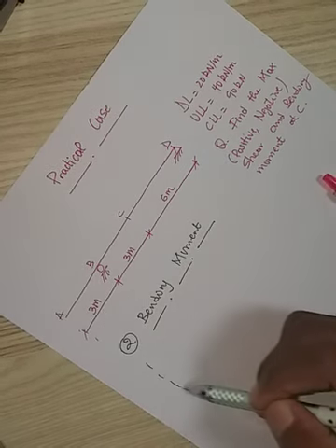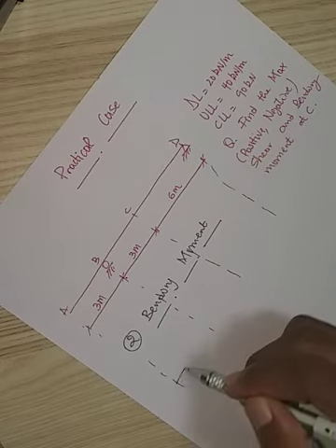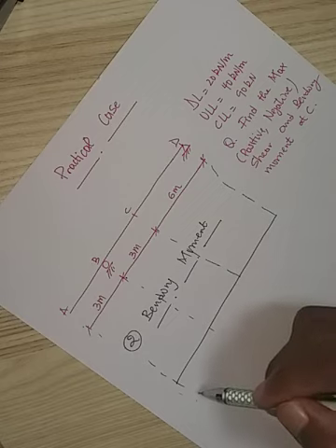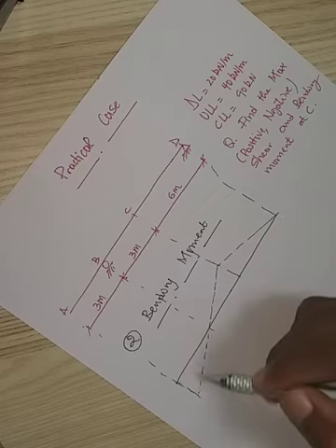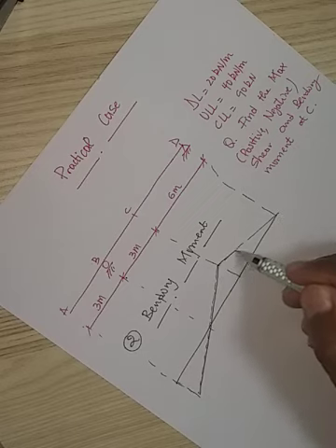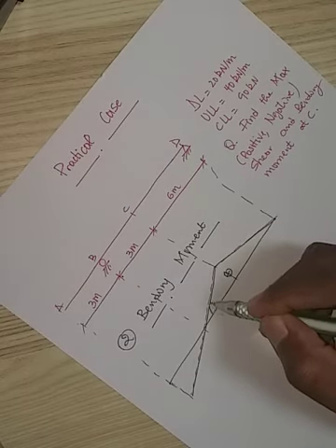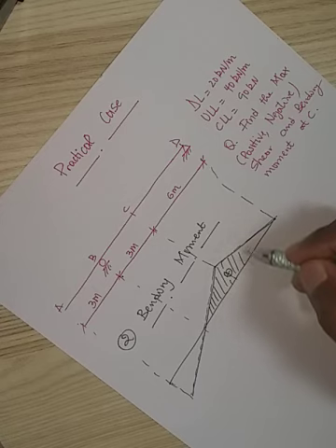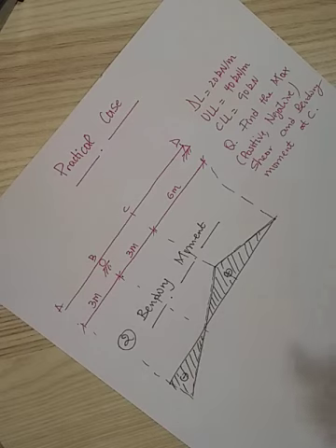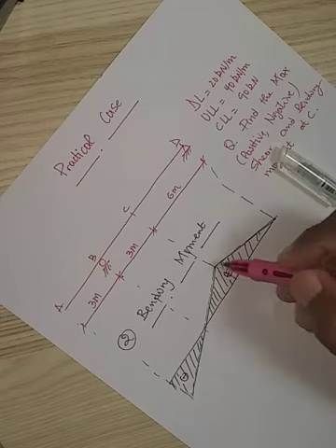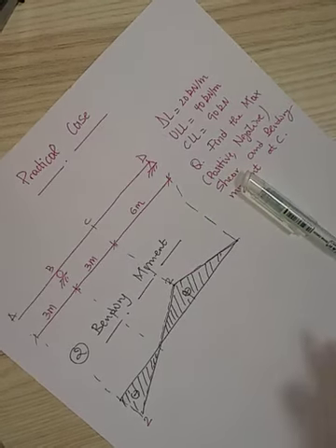Okay, let's draw the bending moment. So this is the shape of the influence line for the bending moment. This is the positive area and this is the negative area. We want to find the magnitude or the value of this peak here. The ordinate actually is 2 and here also is 2. But how did we find it?